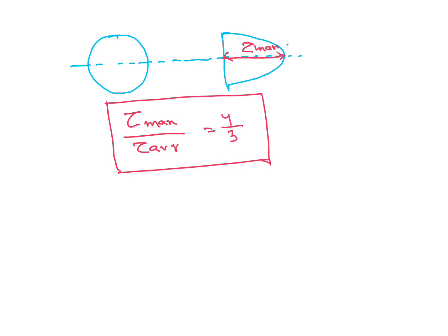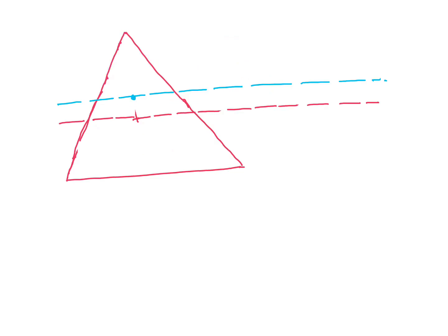And for triangular sections, for maximum shear stress, this is also very important. This is CG point and this is midpoint, or this height is h/2. Here also h/2. Here shear stress diagram, it will come like this. Maximum will occur at midpoint.